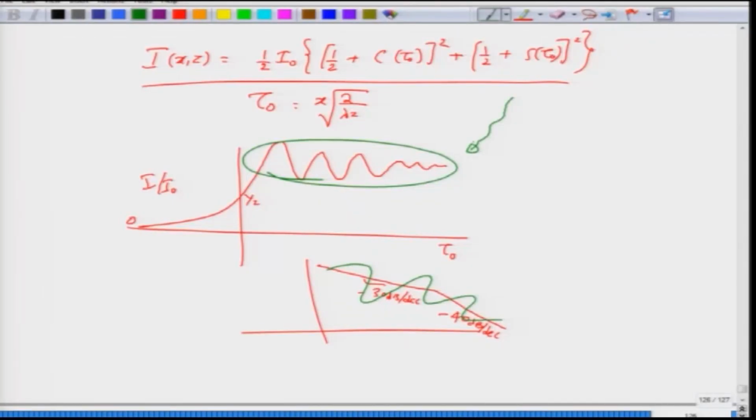So, I admit that this was not a very lengthy mathematical justification for any of this. As I mentioned, it would be quite difficult for us to go into the details in this course, but what you have to understand is that shadowing is not always bad, sometimes it can be good. On an average it is bad, but sometimes it may be good. Therefore, the best case would be that certain areas of the building are good for you and you can have good communication, certain areas will be very bad for you, but determining which one is which is a problem, and on top of it we have multipath fading, which can also change your signal strength very rapidly.